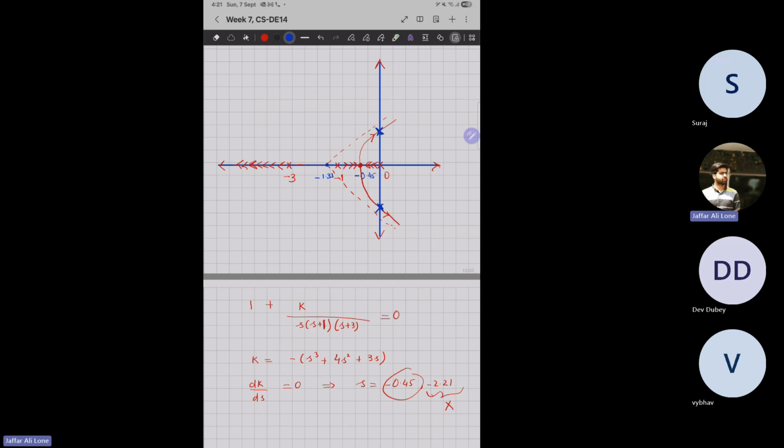Because the root locus will be on the imaginary axis. Okay, so for marginal stability, we have a row of zeros, or we have 0 in the Routh array, and then we find the value of k, and then with that value of k, we can find the value of s, right? So this has already been discussed when we discussed Routh criteria and the auxiliary equation and other things.